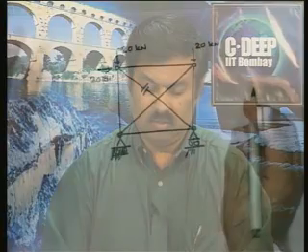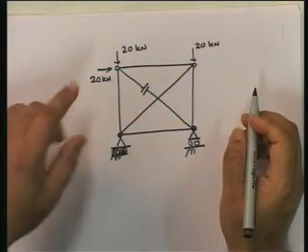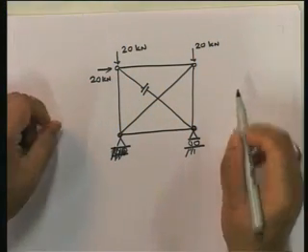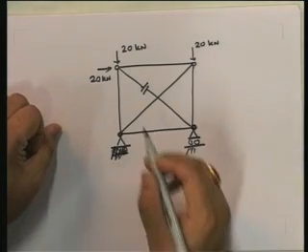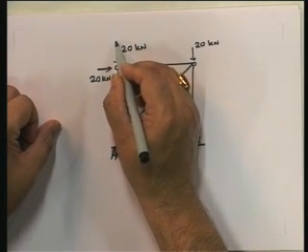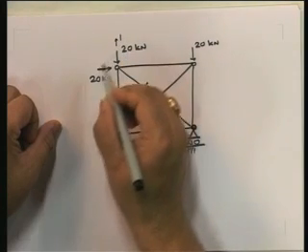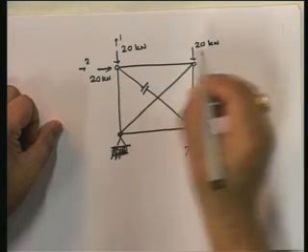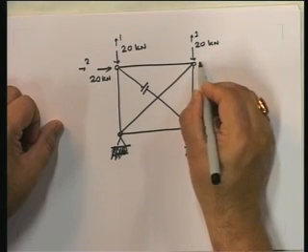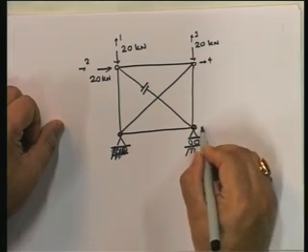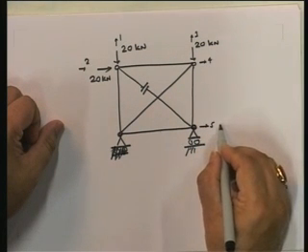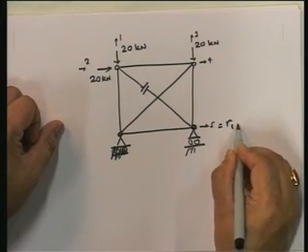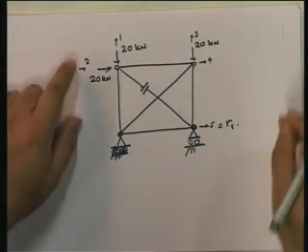method, typically in this particular case it's very easy to solve, because you would have all the degrees of freedom. How many degrees of freedom does this structure have? You will see that this is 0. Here you will have 1, 2, 3, 4 and 5. The 5 is the only one that you've been asked to find out. You've not been asked to find out 1, 2, 3, 4.